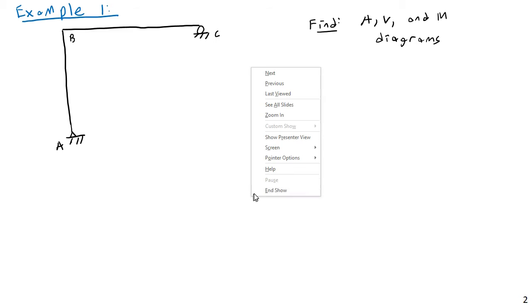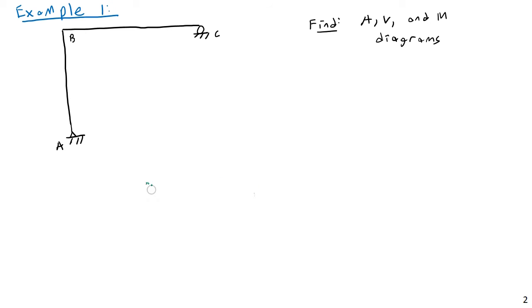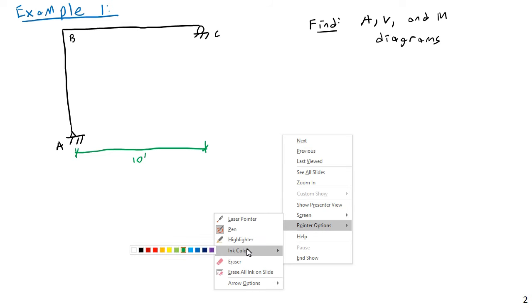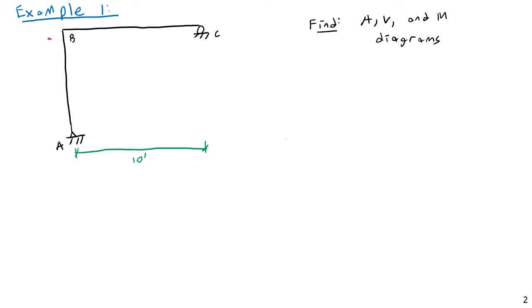Now, of course, we do need to find the loads on here, and we do need the geometries. So we're also given the geometries. The width of this thing is going to be 10 feet. And then we're going to have 2 horizontal loads on here. Let me put the loads in, but then I'll put one more dimension line on here. So let's put a 15 kip point load to the right here and a 10 kip point load to the right here.